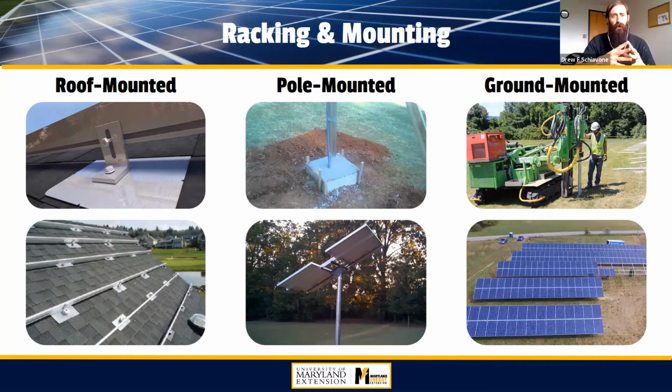And I said there are different types of models there. But that L-foot coming off the roof is then attached by nut and bolt to a railing. You see in the bottom photograph a rail going from left to right across the roof. That long railing is what the module, or the panel, is actually mounted to. We'll look at an example of that momentarily.